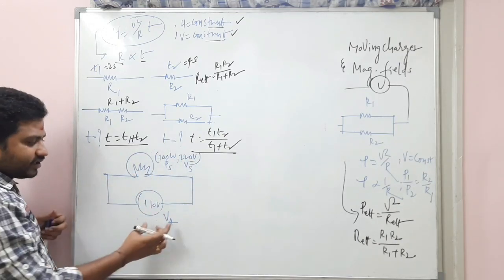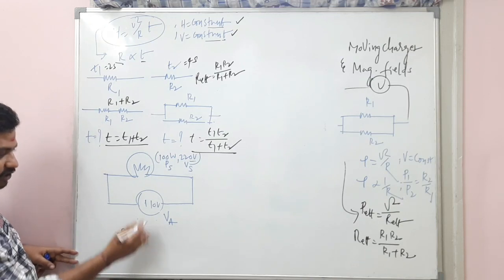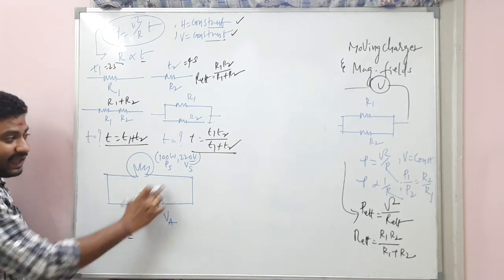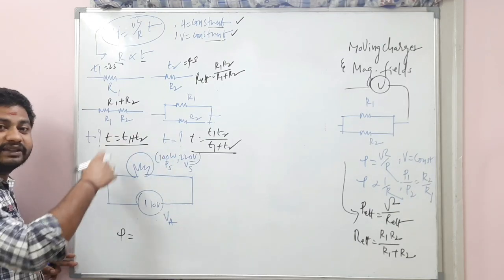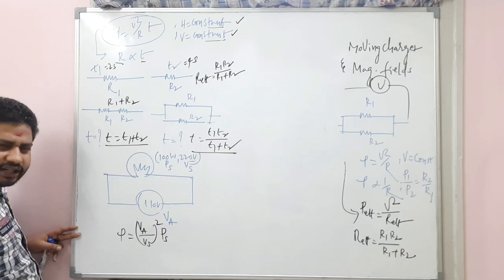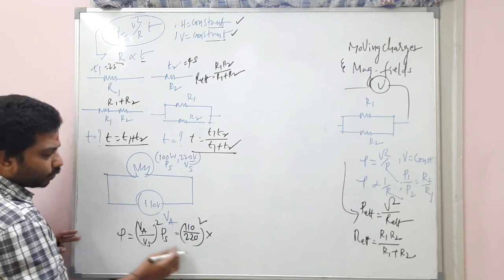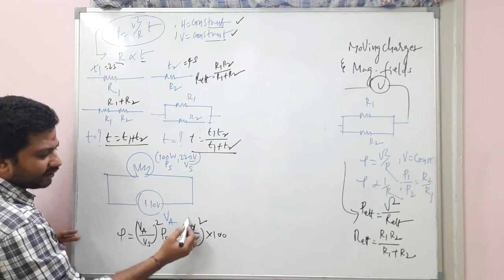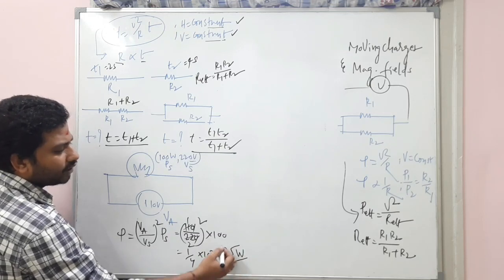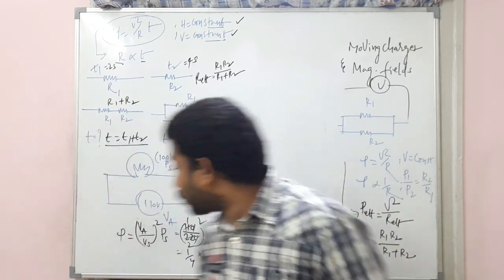So this is the rated power. Now this is the voltage applied. So in this case, power consumed by this bulb is not 100 watt, because here we supplied less than this, as I told you. When you supply exactly 220, then 100 watt is the power consumed by this bulb. So in this case, power consumed formula will be VA by VS whole square into rated power. So what is the VA? 110 by, what is VS here? 220 whole square into 100. The 0 gets cancelled and 1 by 2 whole square, so 1 by 4 into 100. It is how much? 25 watt is the power consumed by this bulb. The power consumed by this bulb is only 25 watt.